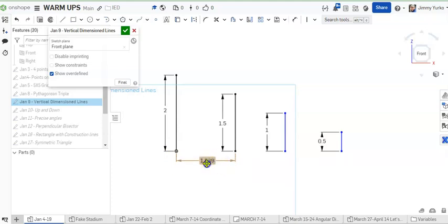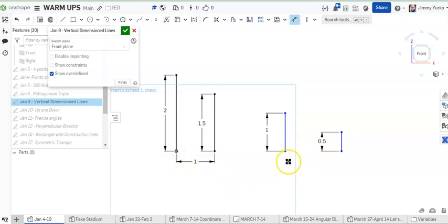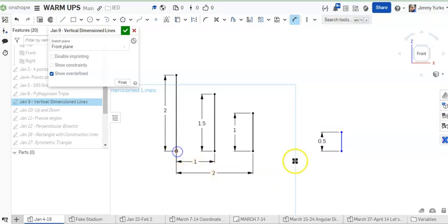No big deal. I'm just going to grab that dimension by the number, put it in the position I want, double click on the number to get the value to be editable, hit the number 1, enter, and I've just added that measurement. I'll repeat that again, hit the D key to dimension, click and release on the origin one time, move the mouse over to the end point of the second line, and release, and then I'm going to click and release in the middle to enter, and repeat.